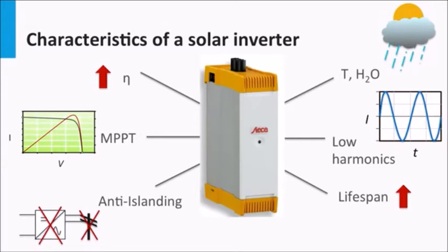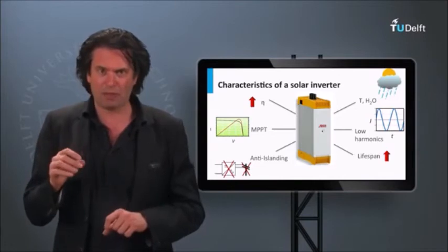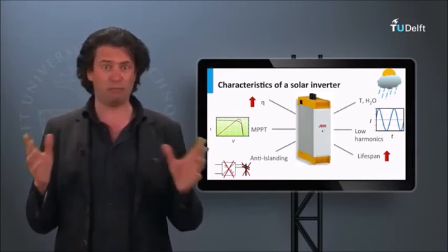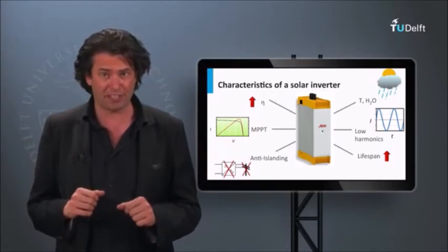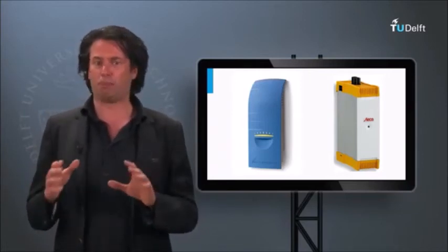It is a work in progress to increase the lifespan of the inverter, the crucial power electronic device in the modern PV system. A good inverter will probably reach, under favorable conditions, around 10 to 12 years of lifetime. This is the bottleneck in the modern PV system's lifetime, especially considering the fact that the PV modules can last over 25 years. We have discussed in this block the need for a solar inverter and also the different types and topologies of inverter implementation.